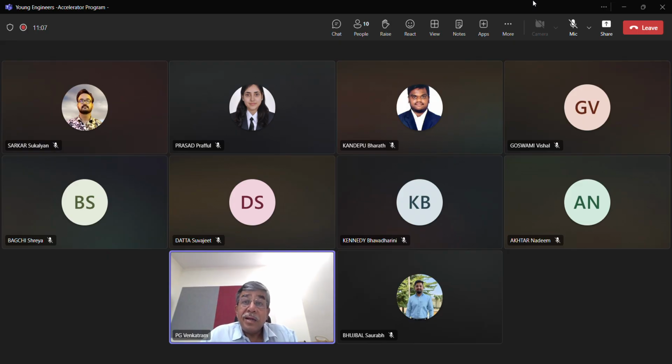Then we looked at unconfined concrete. Then we looked at elastomeric rubber as a load transferring media to be used in bearings and in accommodation of various kinds of deformations. Then we looked at PTFE, polytetrafluoroethylene, as a means to reduce the frictional resistance between the moving components of bridges. These are the things that we looked at.